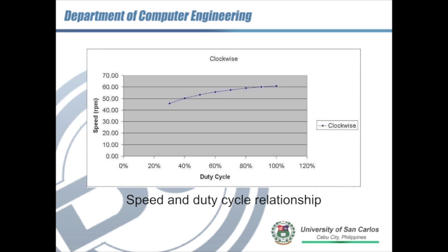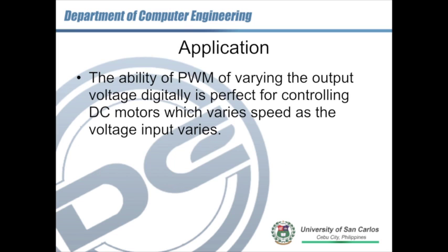If we feed a 5 volt DC motor with 5 volts, the motor is operating at its maximum RPM, since it's designed for a 5 volt source. That is why if we have a 5 volt DC motor and you put a 12 volt supply, it would burn out the motor. If we apply a voltage that's over the rated voltage of the motor, it would burn out.